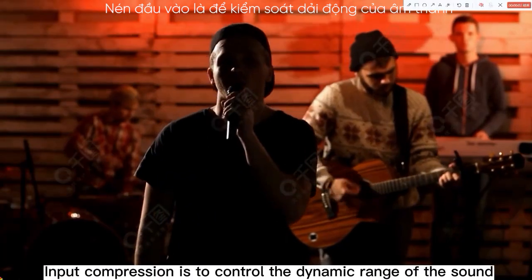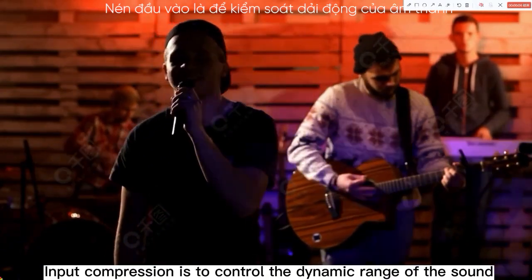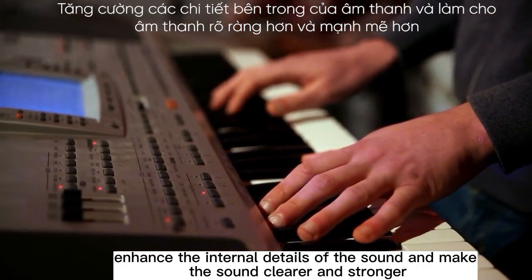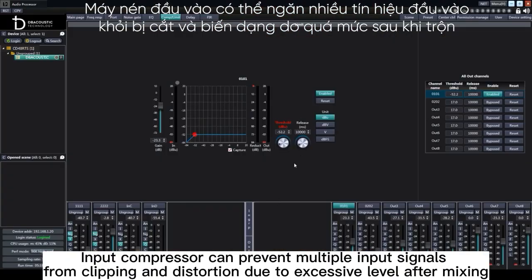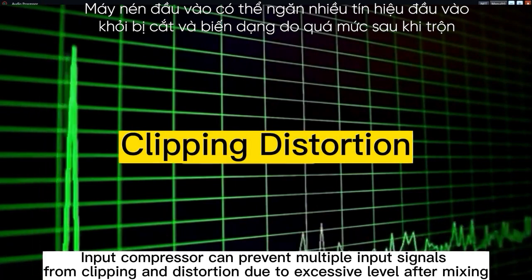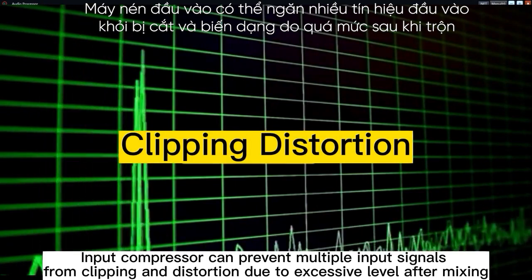Input compression is to control the dynamic range of the sound, enhance the internal details of the sound, and make the sound clearer and stronger. Input compressor can prevent multiple input signals from clipping and distortion due to excessive level after mixing.